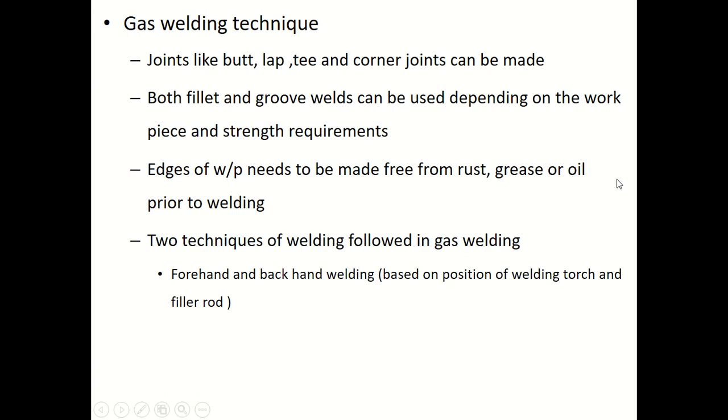Now let's become familiar with the gas welding technique. Using gas welding, you can make joints like butt joint, lap joint, T-joint, and corner joints. Both fillet and groove welds can be used depending upon the workpiece and the strength requirements. And please note that the edges of the workpiece need to be made free from rust, grease, or oil prior to welding. That's very important. If you are going to do gas welding, please ensure that the part to be welded is free from rust, grease, or oil.